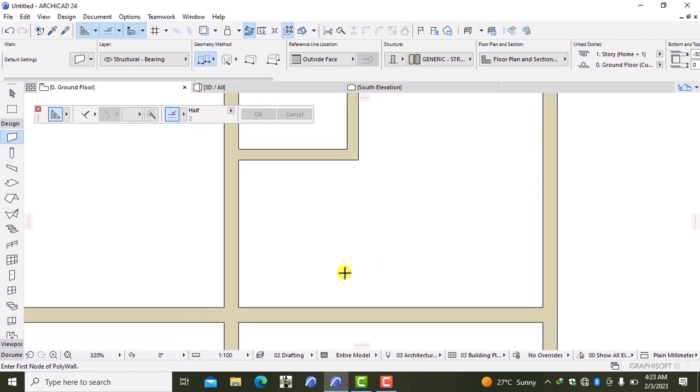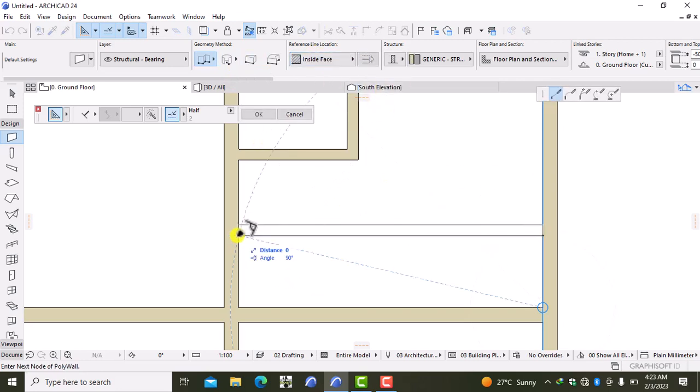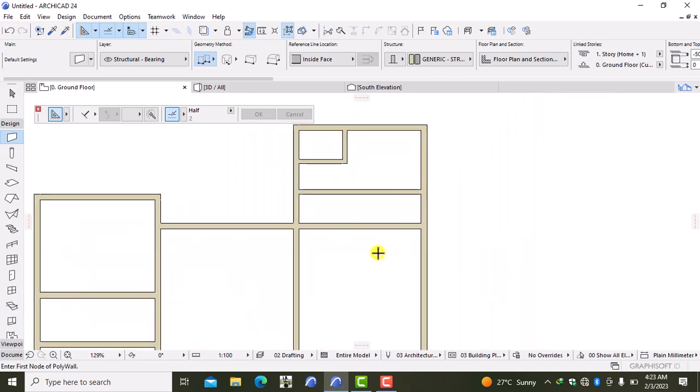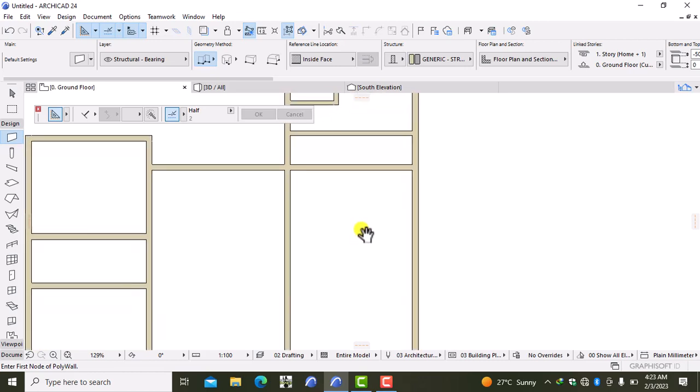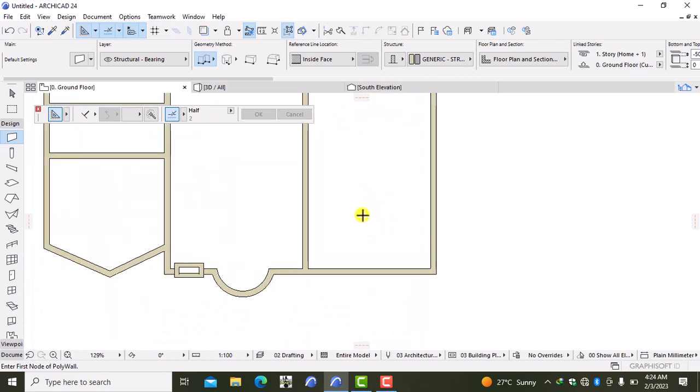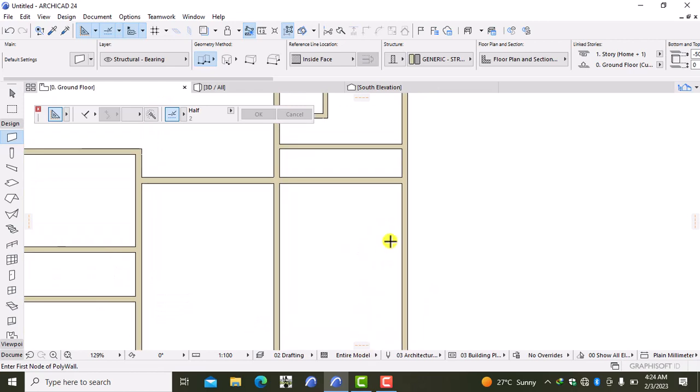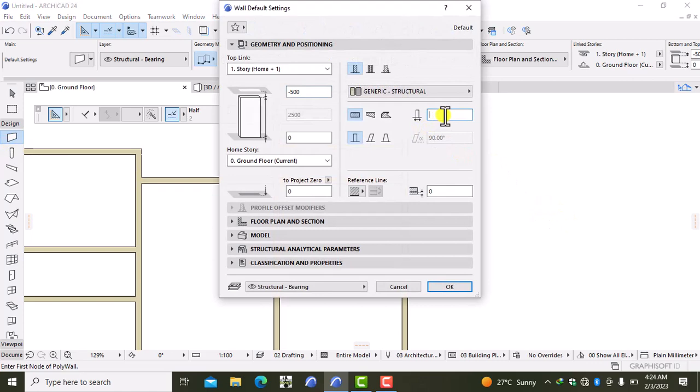Once I'm done with that, I also need to drag another wall from here, a distance of 1000 to a distance of 4000, and I want to change this to the inside face. So yeah, that's the one that I'll be working with there. Also over here, from the kitchen, I have another one which forms part of the kitchen. I'm dragging it at a distance of 1800. From a distance of 1800, I need first to change the wall thickness back to what we had originally, just 200.